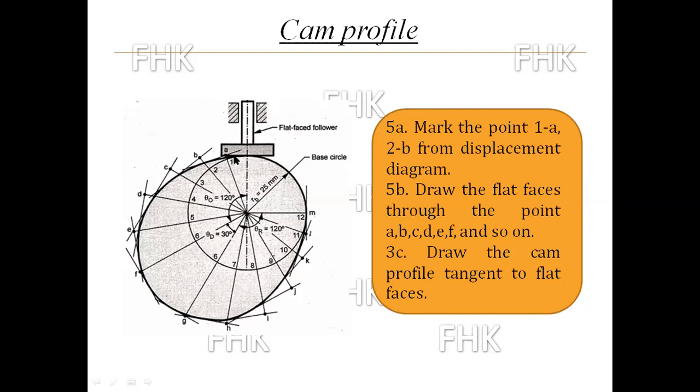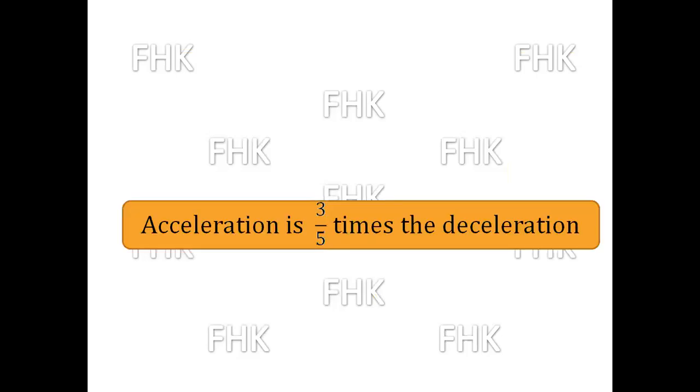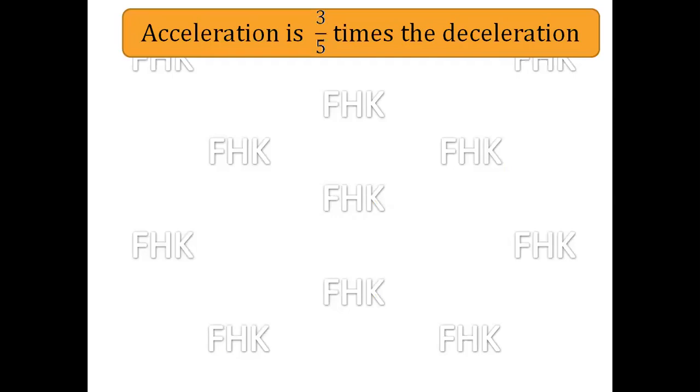You have to draw the cam profile tangent to the flat face for every position, and after drawing the tangency you get a curve like this, and this is the final cam profile for the flat face.